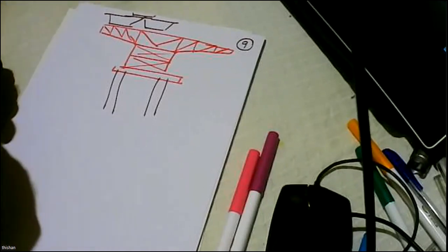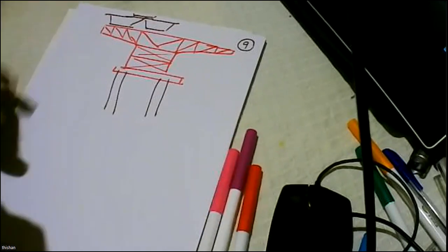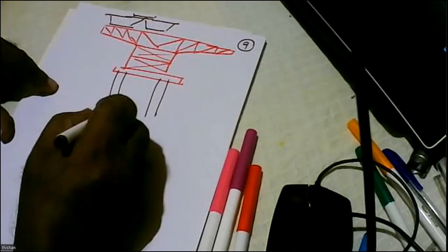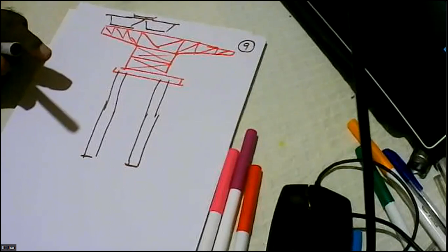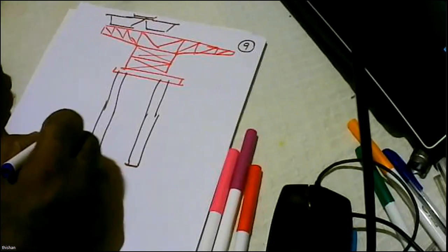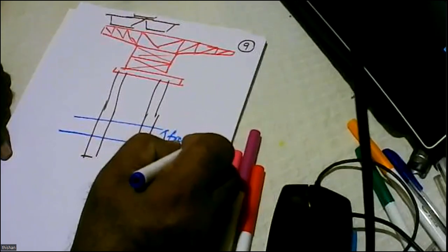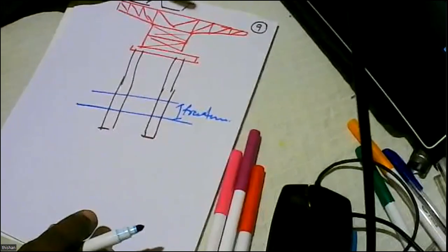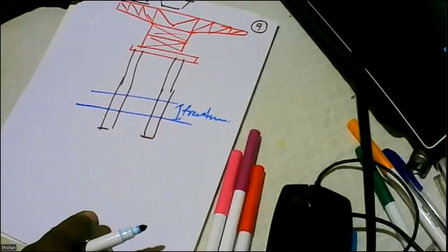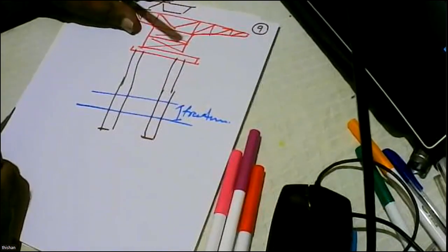So how is the foundation going to respond? But when it comes to the vertical load carrying capacity, you are pretty sure, because you have done some reasonable socketing, and then there's some fractured rock as well. That also can give good skin friction. So you are pretty sure about the piles. But what is not sure is how these piles are going to behave when they are subjected to bending.